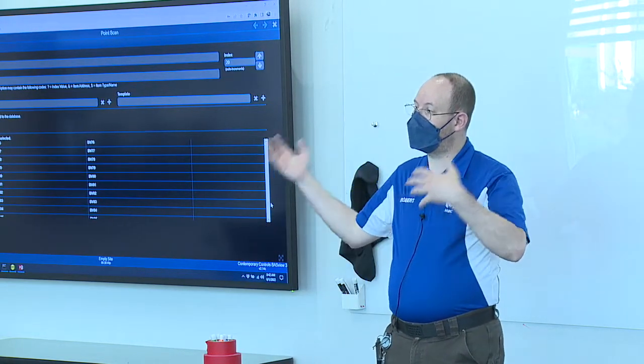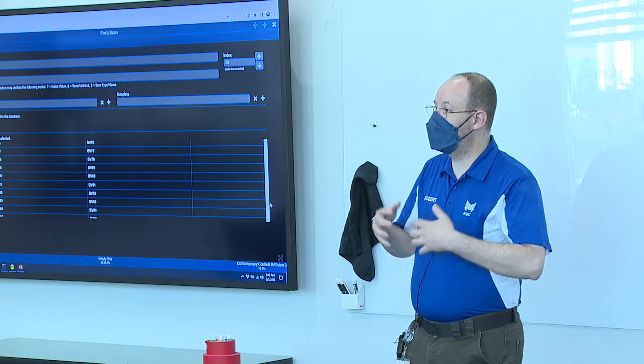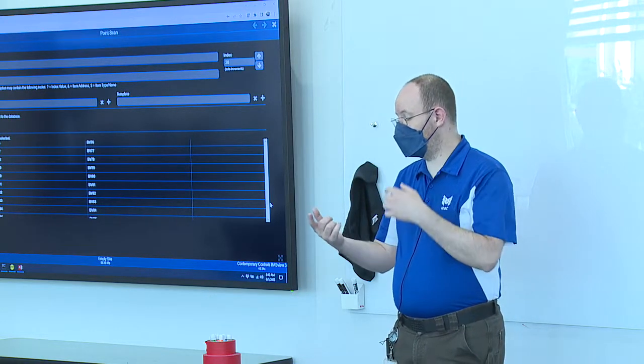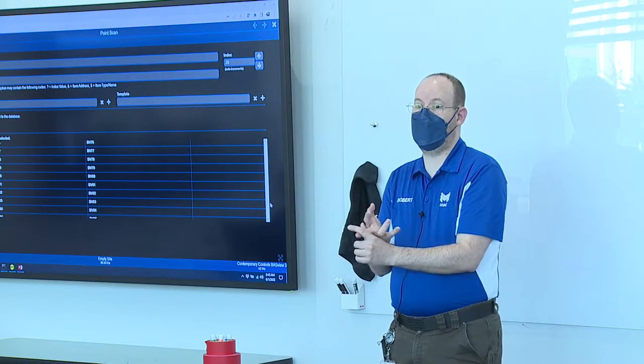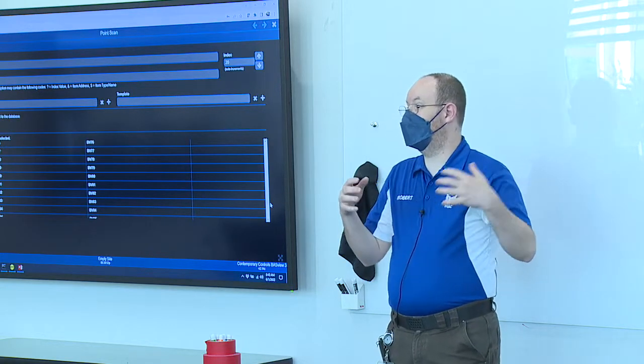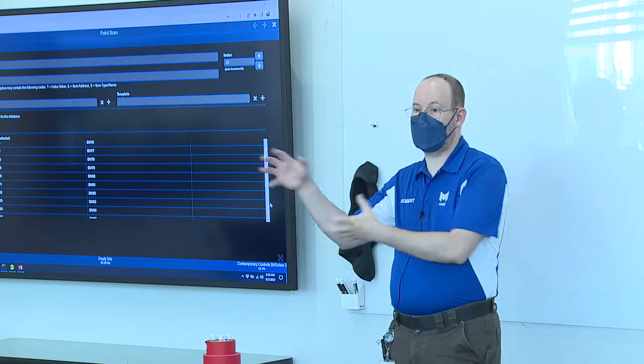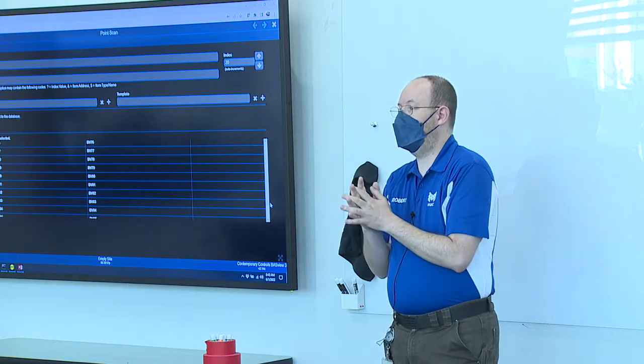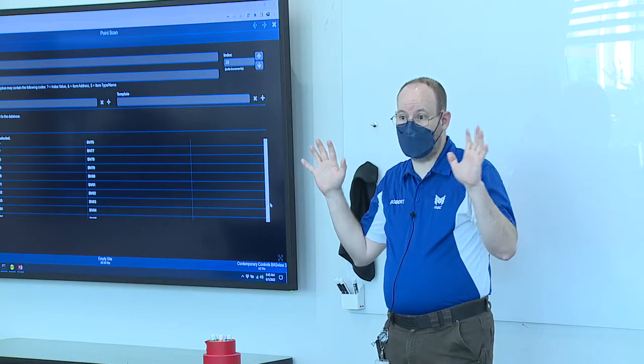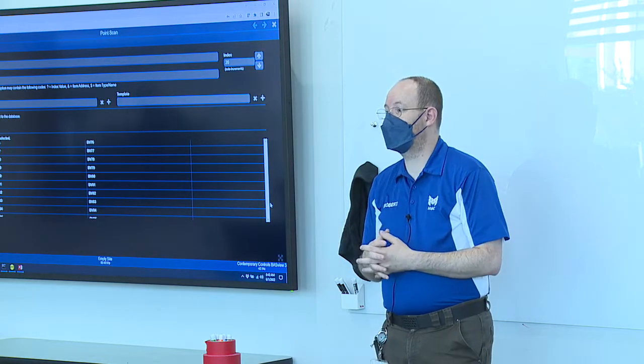If it has full programming options, most of the time it's not going to use schedule objects, trend objects, or a whole stack of the more advanced BACnet objects. Not exclusively, but a lot of the times.